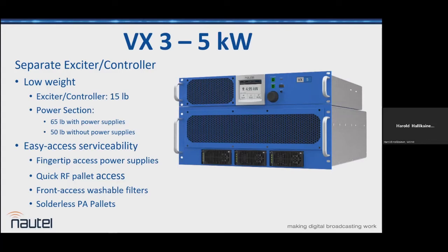These are the mean time between failure. The MTBF calculation numbers are over 80,000 hours, and that's at 50 C, which is 120 degrees Fahrenheit. I think it doubles for every 10 degrees. So if you're running it at a normal 75, 80 degrees, and 8,700 hours per year, you can do the math. It's 15, amazing, plus 20 plus years on the fan by calculation. Now, granted, there are other failure modes, but from a wear-out mechanism, that's pretty good.